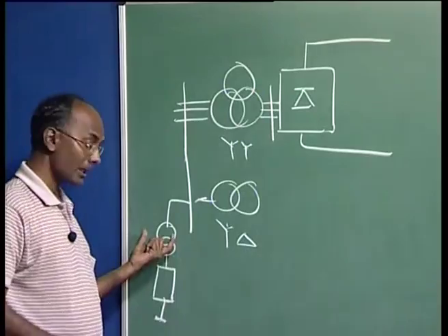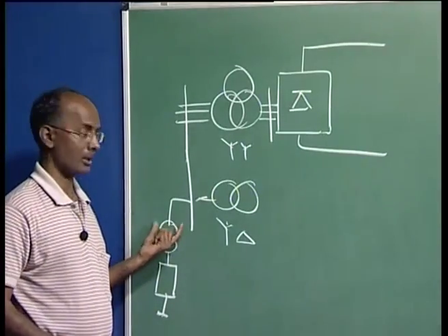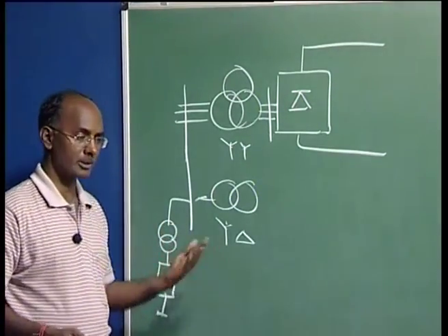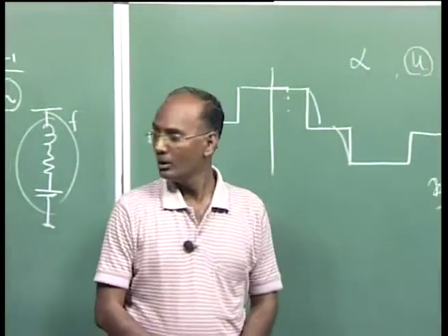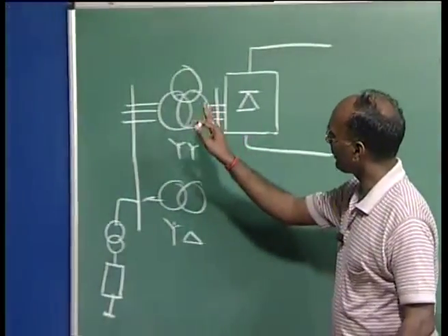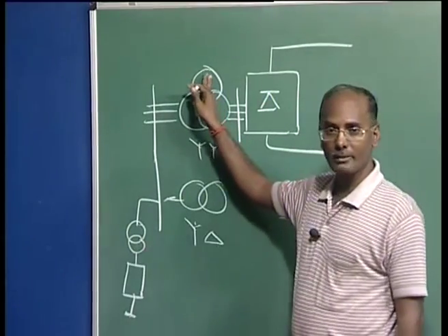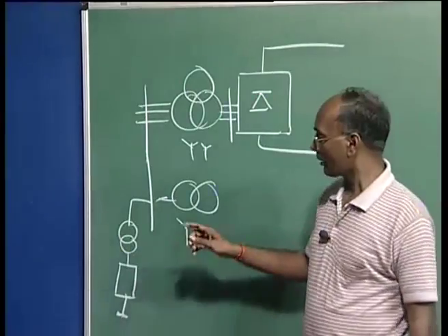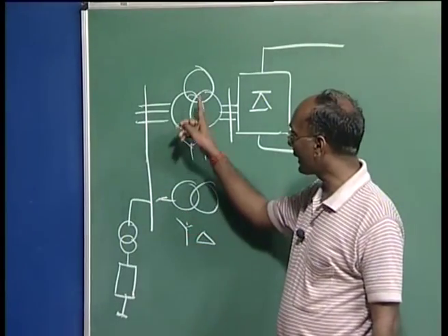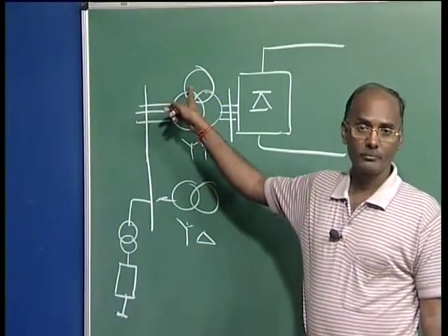So then you are incurring extra cost here, because from 400 kV you are going to maybe 66 kV or 33 kV, and then you are connecting the shunt filters there. So if the filter is used in the tertiary winding, because the voltage is low, you are minimizing the cost compared to this transformer. No doubt if you are adding another winding, the cost will be more.